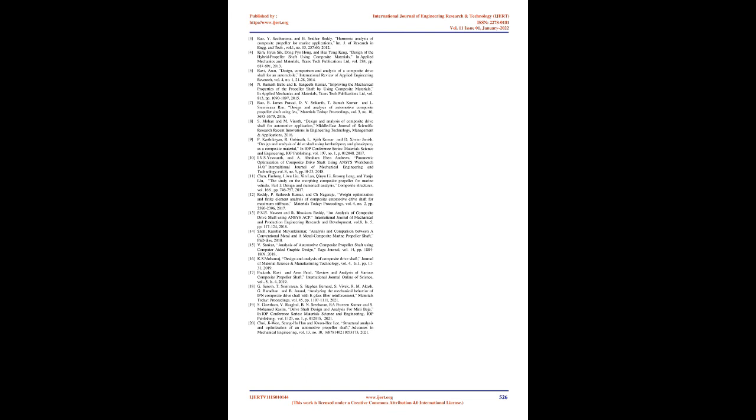The following types of loading can be used in static analysis: external forces, moments, and pressures. Gravity and spinning are examples of steady-state inertial forces. Non-zero displacements were imposed. If the stress levels derived in this study exceed the permitted limits, the structure will fail in the future. Figure 6 shows the torsion analysis of steel shaft. Figure 7 shows the maximum principal stress of steel. Figure 8 shows the maximum principal strain of steel. Figure 9 shows the equivalent stress of steel shaft. Figure 10 shows the total buckling deformations of steel shaft.